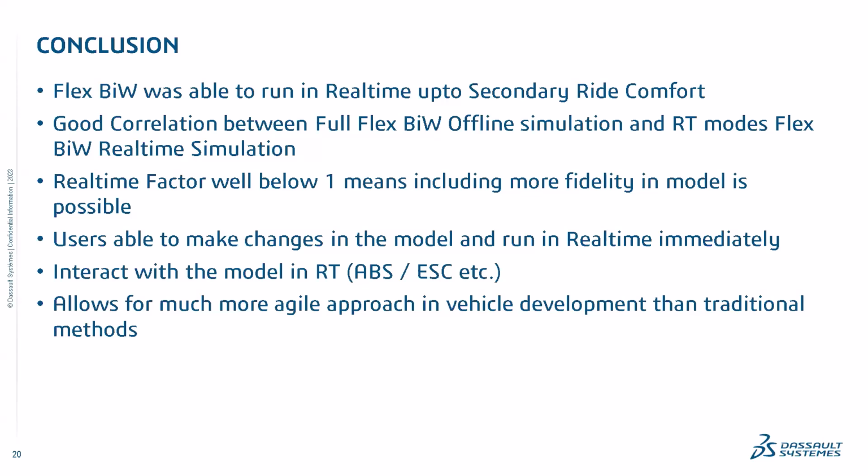Real time factor was well below 1, which is very important. The real time factor, which was coming out to be 0.87, should always be less than 1. The fact that it was 0.871 means that we could include more model fidelity into the model, and that was possible.